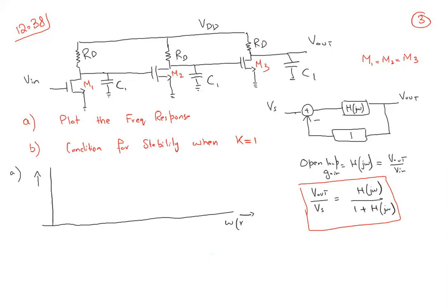Omega radians per second. So we have the magnitude plot. I am drawing again the open loop, so I'm writing explicitly magnitude of h of j omega. We know that we have 3 poles here, and we need some starting point, and all of these 3 poles are lying at the same point. If we just see these node points, we have one node here.